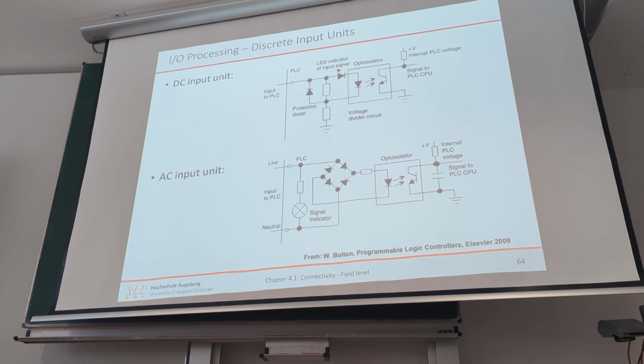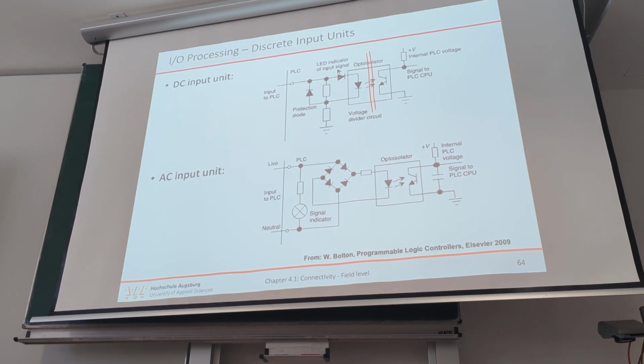And then we have this protection circuit. Usually we use opto-isolation. So here the signal at that part is actually completely electrically isolated. The signal is passed into a photo diode, or into a diode, and only the light basically then surpasses the barrier towards a phototransistor.